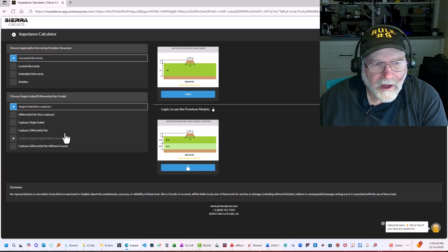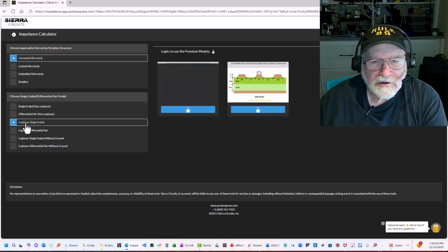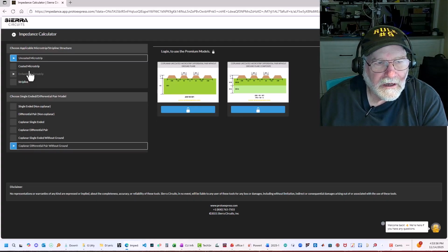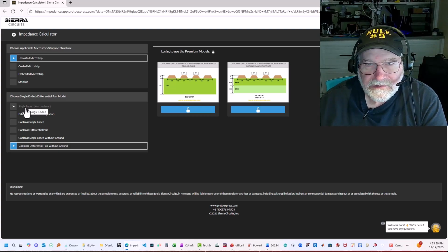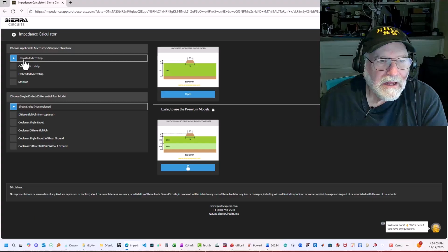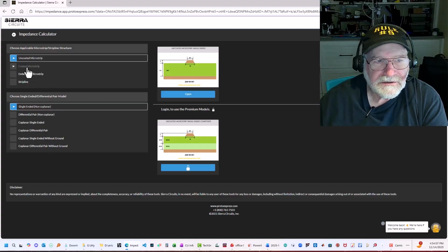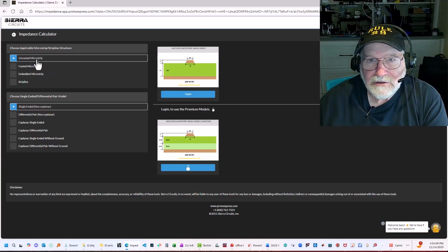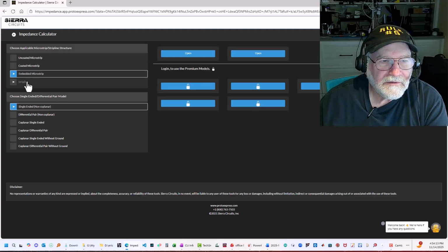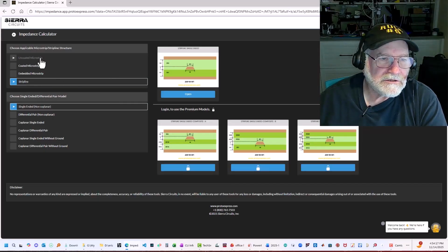Over here in the bottom part, we can select what kind of transmission line: single-ended, differential, coplanar. You see the different geometries that are available here. We're going to do something really simple and just do single-ended initially, and then you can peruse this and evaluate at your leisure. And then given the type of cross-section, we can have different features. We're going to look at the case of the uncoated microstrip. Coated just means there's a solder mask on top, there's embedded, and there's strip line as well. So these are the variety of predefined structures that are involved.